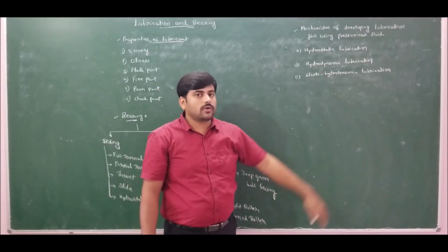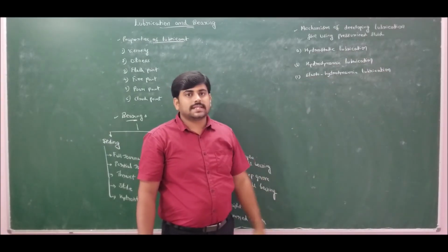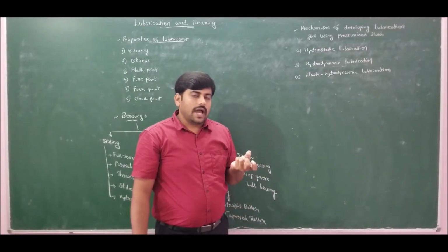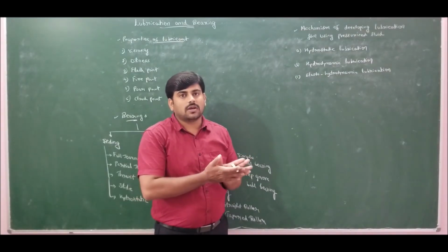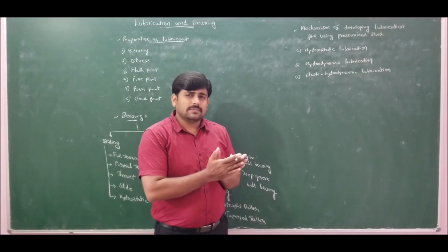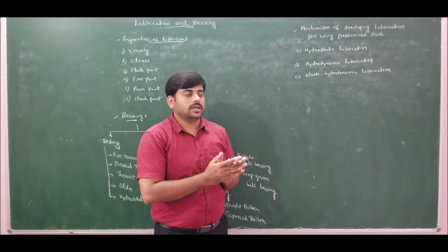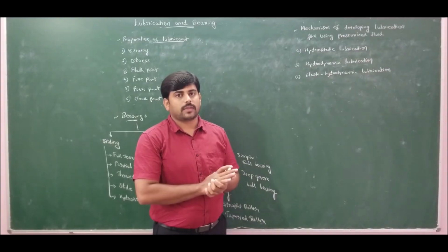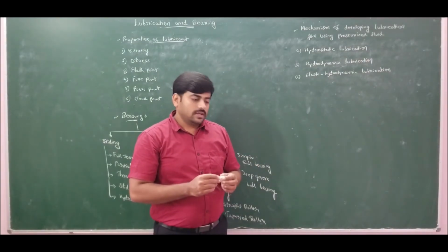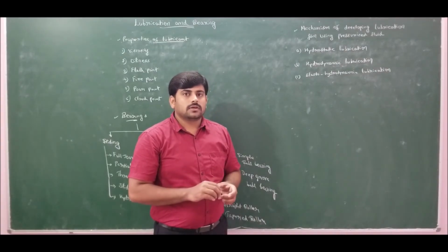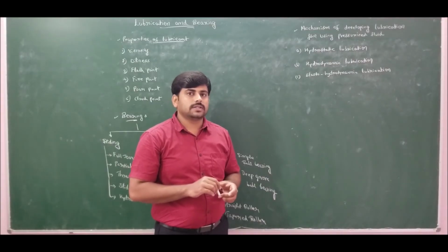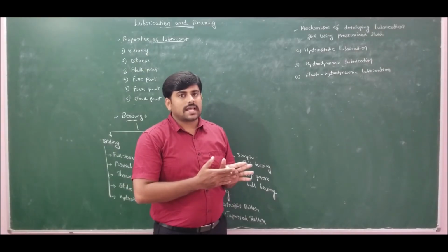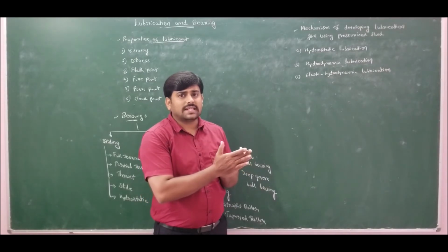Next, coming to elasto-hydrodynamic lubrication. As the name elasto states, when the bearings are subjected to loading conditions, the journal has some elasticity in it, which causes flattening of the journal. So this negligible flattening and the very high viscosity of the lubricant will cause a thin film of lubrication between the journal and the bearing. As we all know, if I analyze a mild steel in a UTM, we observe the elastic limit and later we observe the yield point. Similarly, when the journal is subjected to loading conditions, it will have some amount of elasticity, which causes a negligible flattening of the journal.